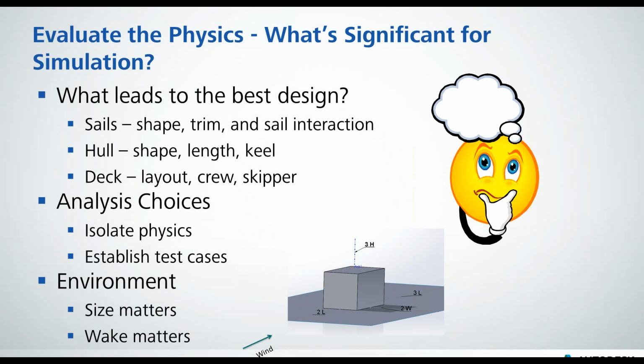So when we're trying to do the simulation, if we really haven't captured the wake, we really haven't captured what's going on with the flow, and our answer won't be as accurate. So that's why we ask the box to be a little bit longer to capture that wake. So all of this is the thinking part before we even are looking at our CAD.